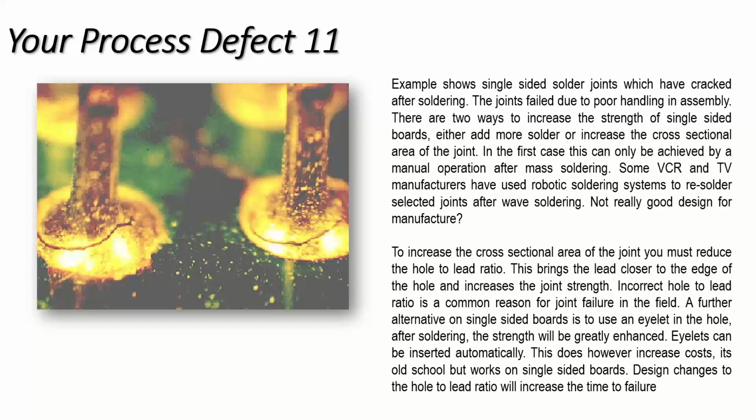So having an automatic eyelet machine and inserting eyelets to make 5 or 6 holes in a printed circuit board, which has got heavy components on, is not as significant a cost when you look at amortizing it over a long run of products. Or alternatively, if it's a small run of products, then you could easily do this yourself. It's not difficult to do.